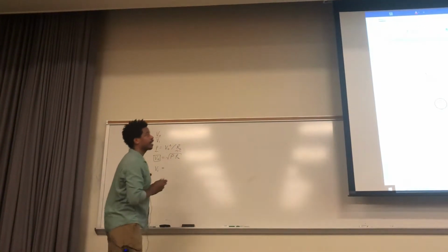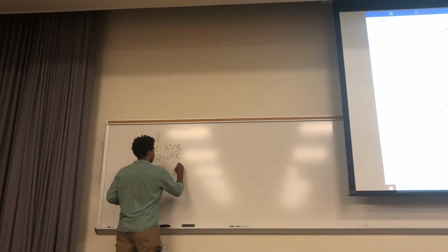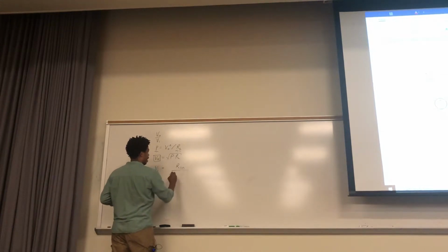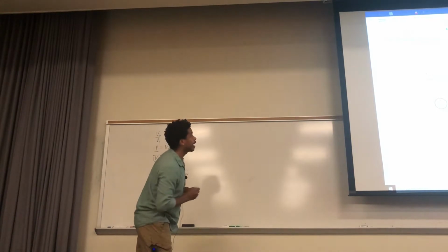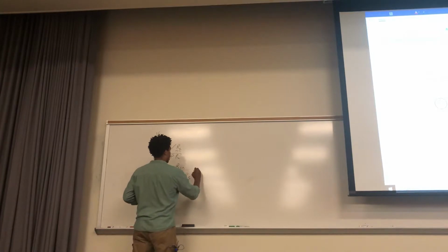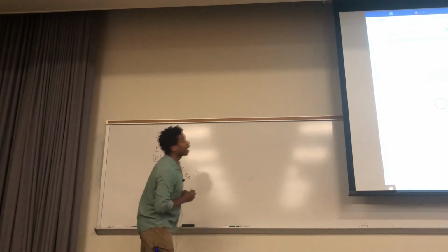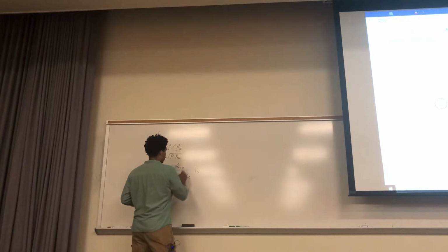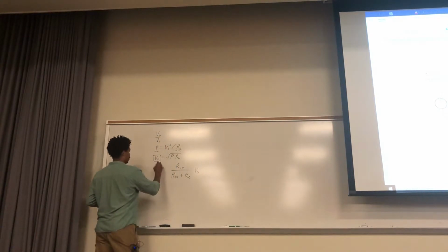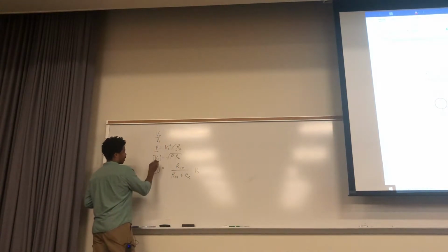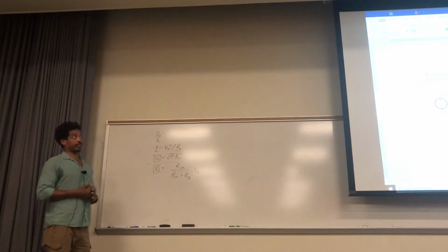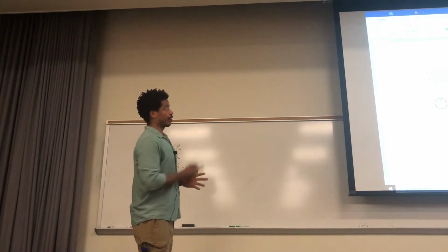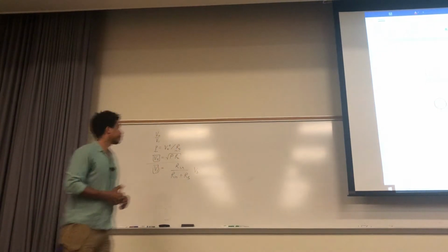So we can say that Vn equals Rn divided by Rn plus Rs multiplied by Vs. And we know all of these values. So it's a ratio between those two things, and that's going to be your first thing, your voltage gain. And you just plug in your numbers.